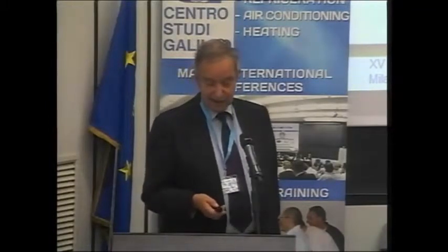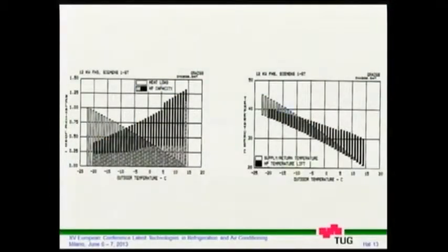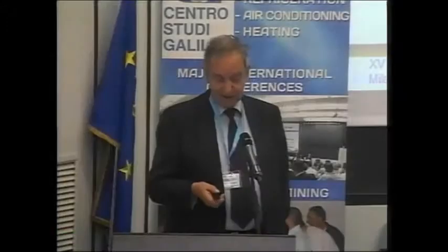You have minimum temperatures of below -20, and the heating boundary is somewhere in the range of 20 degrees centigrade. And if you now integrate an outside air heat pump directly in such a circuit, you can see that the load, which starts at about 15 degrees centigrade, rises up to its 100% value at -22, and the capacity of the heat pump is remarkably higher.